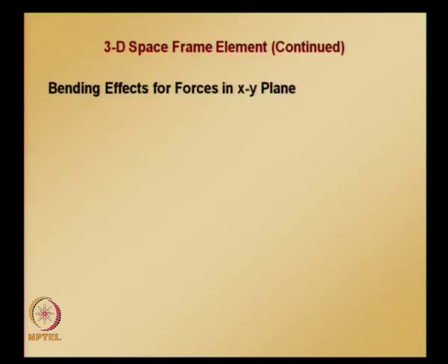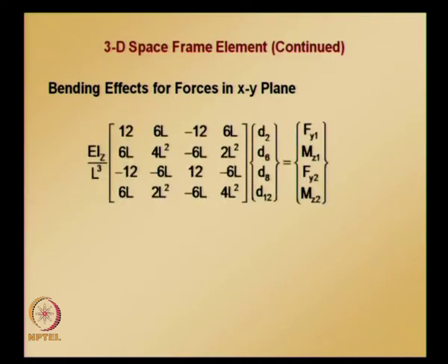for bending effects in the xy plane, it is given by this equation, and since the rotation is about the z axis, we need to use the corresponding moment of inertia when we are calculating flexural rigidity EI.